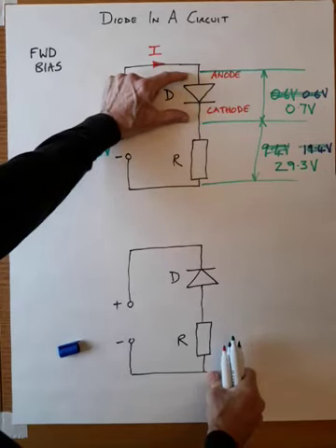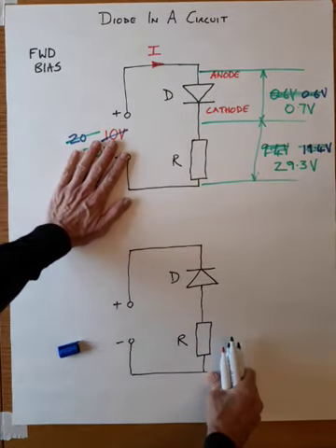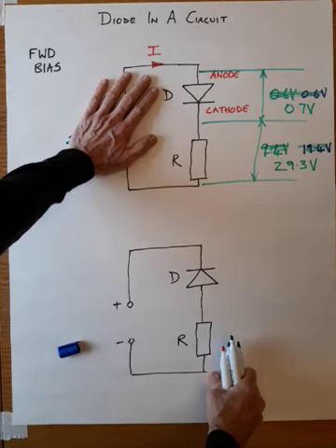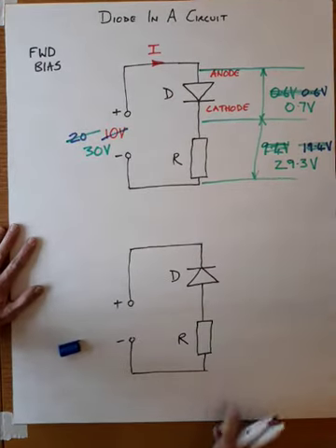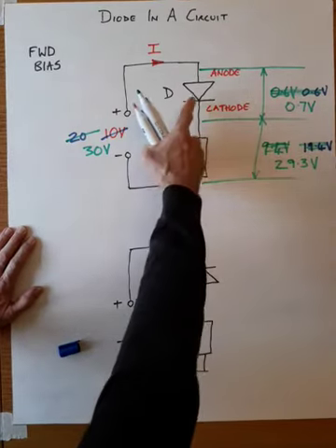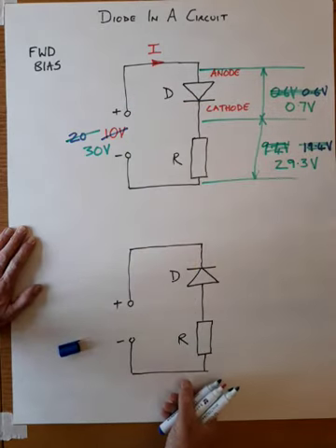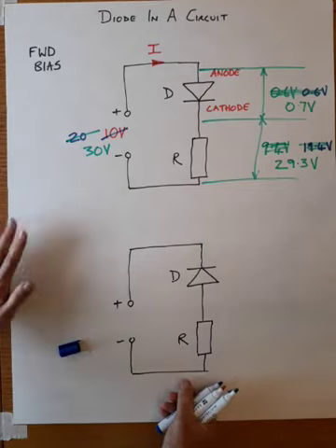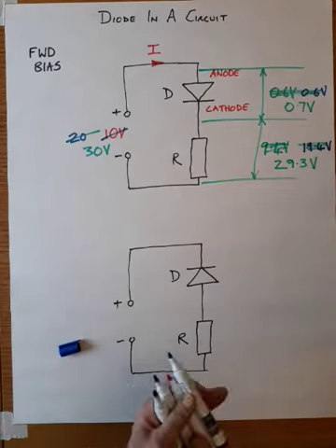So there is a clear point here, and the point is that once the diode is conducting, the potential difference, the voltage across it, is fairly constant at around 0.6 volts. If we apply sufficient voltage and pass sufficient current through the circuit, it will creep up to 0.7. But for this course, for the level that we're at, 0.6 volts is the magic figure at which the diode turns on, and it holds the voltage across it fairly constant. So that was forward bias, turning the diode on and making it conduct.